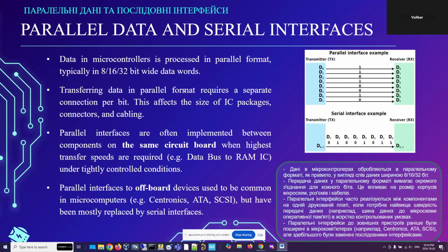And as long as the data is in parallel format, it requires a separate connection per bit. That means the packages for the integrated circuits are larger, the wider the data width becomes that is being processed inside those microcontrollers. It affects the size of connectors and it affects the size of cabling.